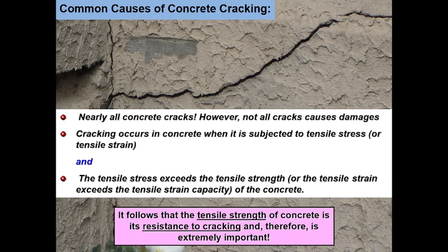And before we start, we need to emphasize the fact that nearly all concrete cracks. However, not all cracks cause damage. Why? Cracks occur in concrete when it is subjected to tensile stress or tensile strain, and the tensile stress exceeds the tensile strength of the concrete, or you might say the tensile strain exceeds the tensile strength capacity of the concrete.